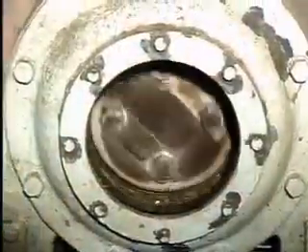Fast-moving gears such as these can build up quite a bit of heat from friction caused by the teeth rubbing together. The oil picked up by the gears not only lubricates them, but also carries the heat away. Oil is also important as both a coolant and as a lubricant in bearings. These bearings support large, heavy rollers. The friction produced by the heavy load can build up a lot of heat in the bearings, but the lubricating oil flowing through helps keep them cool.